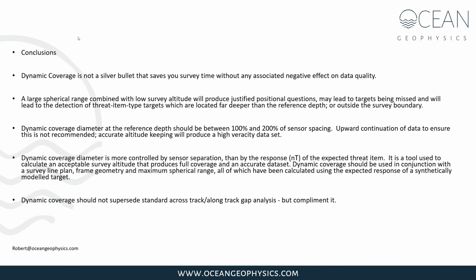In conclusion, dynamic coverage is not a silver bullet that saves you survey time without any associated negative effect on data quality. A large spherical range combined with a low survey altitude will produce justified positional questions, may lead to targets being missed, and will lead to the detection of threat item type targets which are located far deeper than the reference depth or outside the survey boundary. Dynamic coverage diameter at the reference depth should be between 100 and 200% of sensor spacing. Upward continuation of data to ensure this is not recommended. Accurate altitude keeping will produce a high veracity dataset.